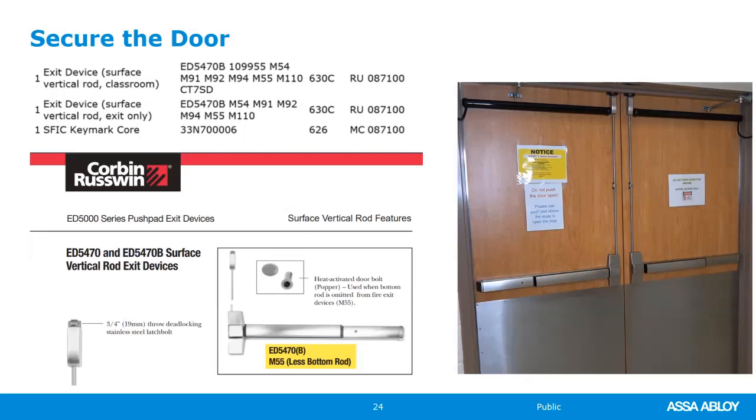So after the first 5 minutes of the furnace getting to 1,000 degrees, the test furnace, rather than ventilate the smoke and hot flames and gases out of the top of the furnace like a chimney, it moves the pressure plane down to 40 inches above the sill, and wood doors have to have concealed intumescent, which expands to seal the gaps, so that the cool air is being sucked in underneath the door, but the hot smoke and the hot gases cannot be forced out through the top of the door.